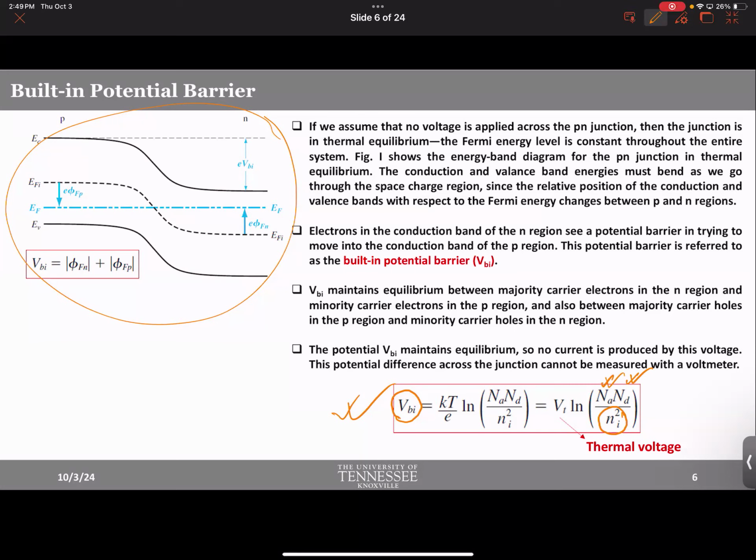Okay, there are reasons. One of the factors is that intrinsic carrier concentration has a big role to play. So if you move from silicon to germanium, you immediately change the turn-on voltage. Oftentimes, if you need a lower turn-on voltage diode, you dramatically change the material. Okay. Anyways,